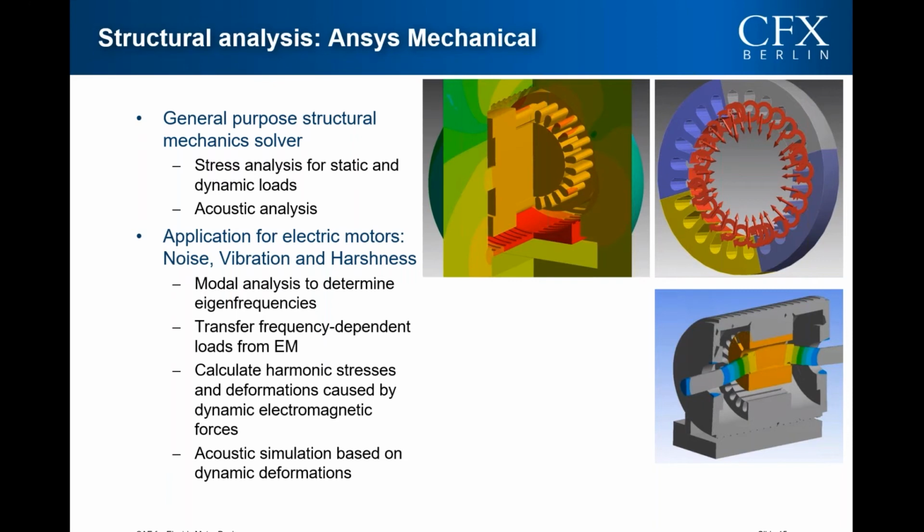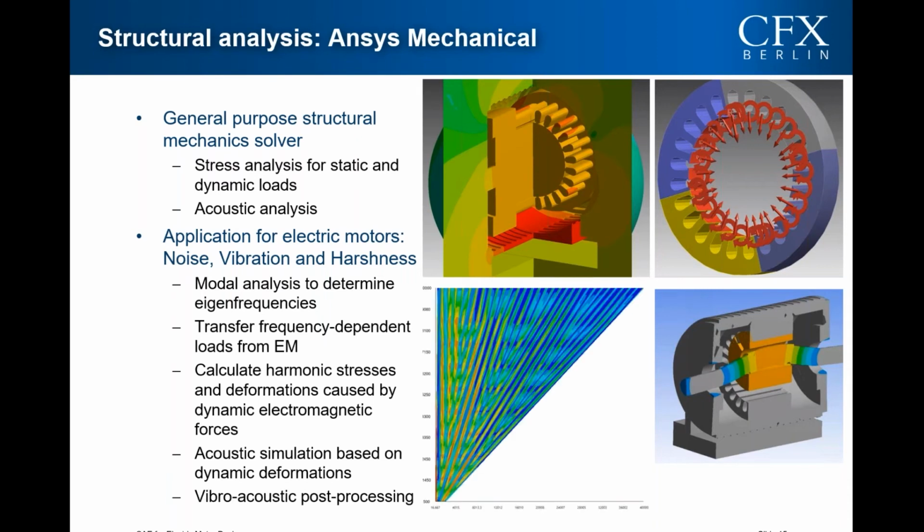Acoustic simulations based on dynamic deformations can predict the sound pressure levels outside the machine. And finally, vibroacoustic post-processing is available by means of a waterfall plot. The color shows the acoustic amplitudes for a given frequency that belong to certain machine speeds. It helps us in determining the noise that occurs for different machine loads.